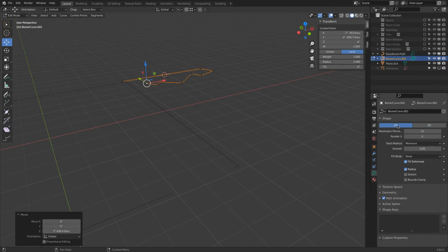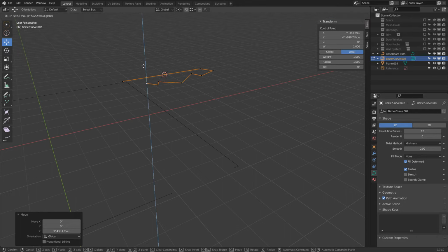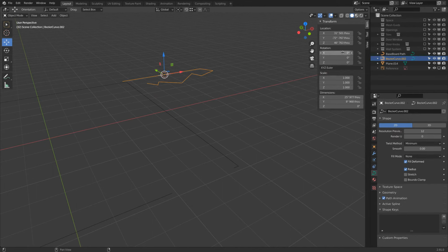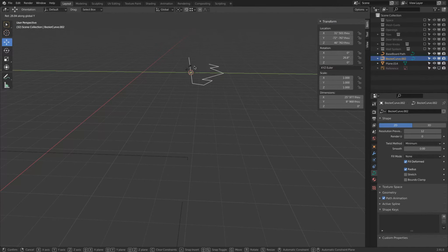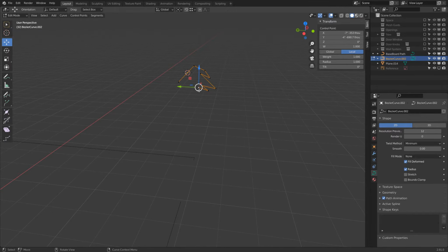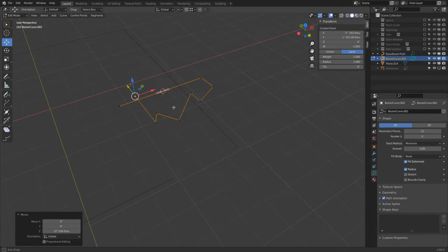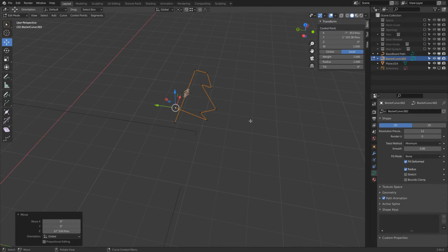If I click this 2D, it is truly a 2D curve. This object was created from the top. It has no rotation. If I rotate this, RX, go into edit mode, I can't move this up, but I can slide it. So this actually pretty much behaves like the sketches in Fusion, which are two-dimensional too.